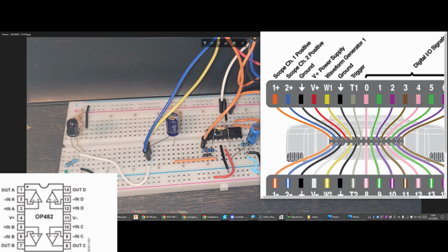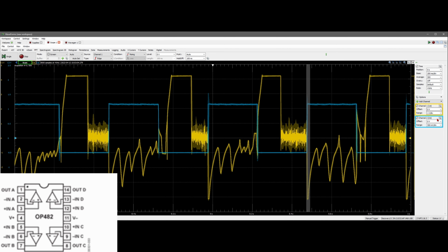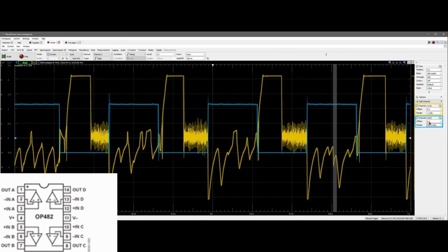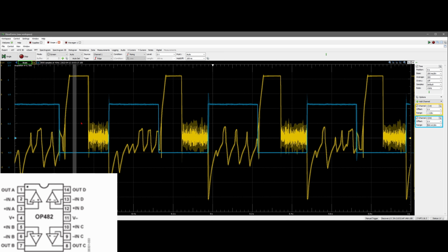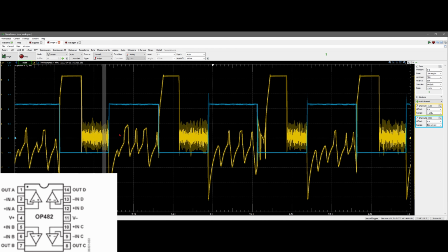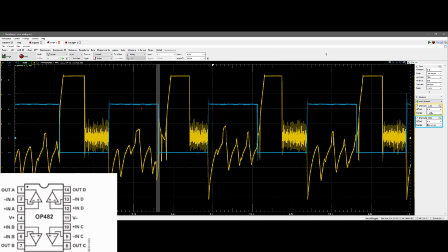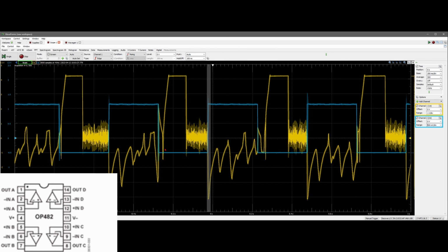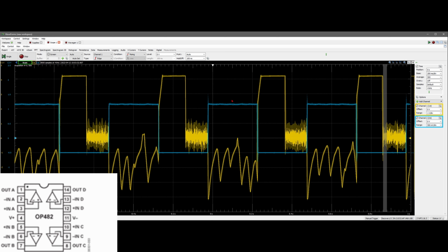And so if we go back to our WaveForms, the settings I have are 0 volts, 1 volt for channel 1, 0 volts, 500 millivolts for channel 2. Our supplies is the same. Our wave gen, I've changed it to be a square wave, and 1 volt on the amplitude for this test right here. And we can see that we have some noise right here. We're going to eliminate that hopefully with the filters. And then we also have, right after this cycle, some strong input where it goes up like this. And that's it for all of them.